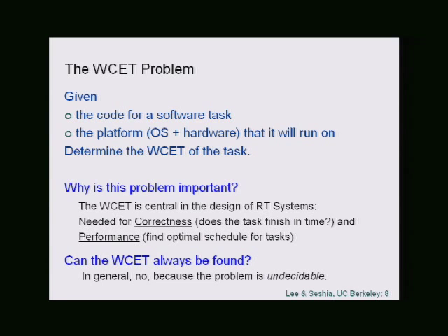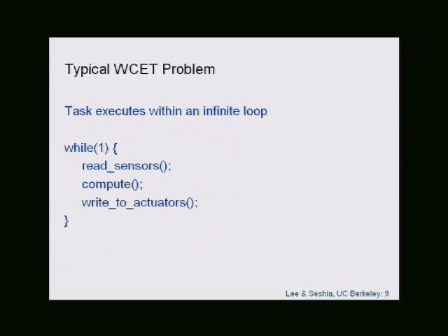Although I can see that a lot of you are really embedded systems people because you make the right assumptions about programs already, right? So it took a while to get to the halting problem here. And so the thing is that in embedded systems, the parts of the code that you're interested in putting real-time bounds on are usually very carefully written so that they do terminate, in the sense that you write loops where you know the bound on the number of iterations the loop will take. And if you use recursion, typically recursion is disallowed, but if you do use recursion, then you have to think about what the recursion depth is, how many times the function is going to recurse.